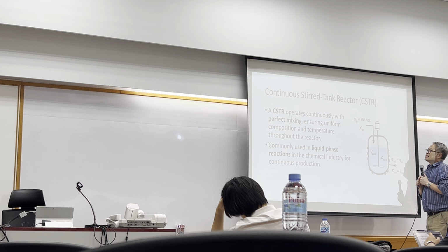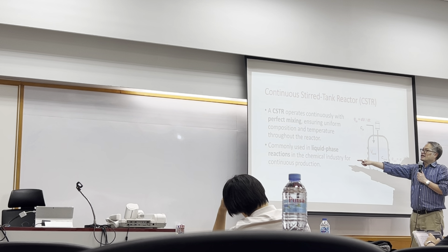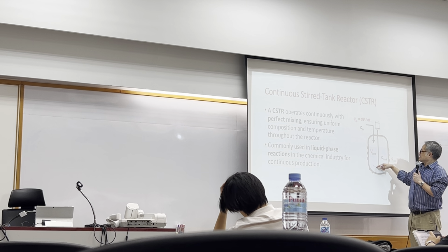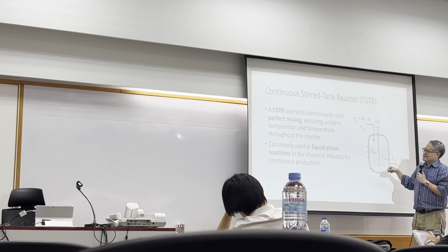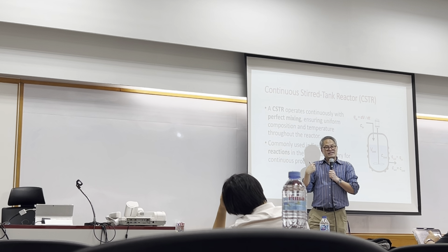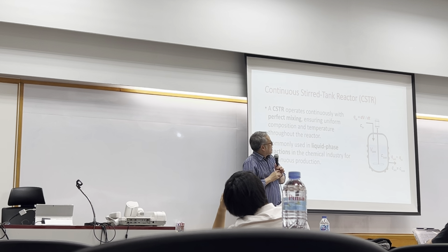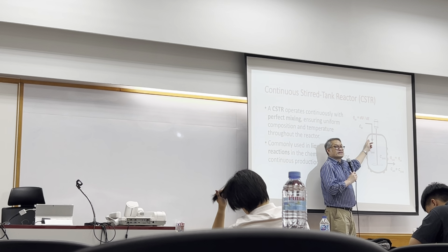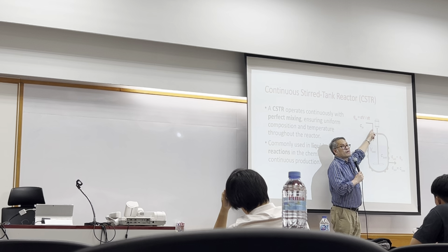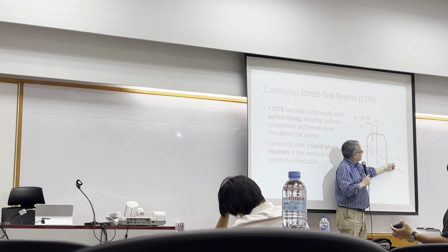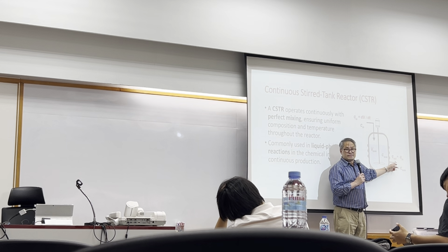Commonly used in liquid phase reactions, because, as it looks here, it's liquid. For gas phase reactions, we usually go forward to the tubular reactor. But for the CSTR, there will be an inlet. You feed your raw materials here, you let them react, and you have some product coming out.